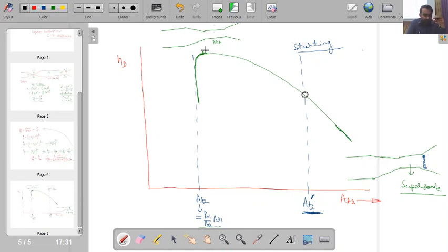Now there are some sophisticated diffusers where you can have some mechanism to have a variable area of the throat section. So you can have some additional arrangement which will give you the area of the throat equal to A2 dash during the starting phase.